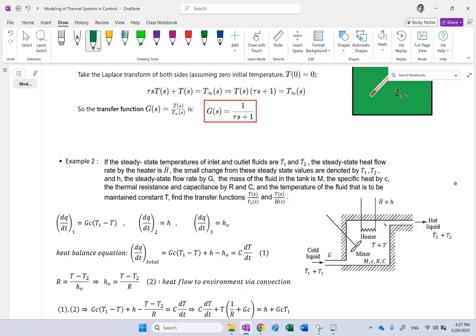One is that you have a heater in the system, and that heater is a heat source, and it generates heat and makes the system temperature go up, where the system stores that like a capacitor. Another way that the system exchanges heat with the environment is through convection or conduction with the environment, okay? So that you can model by a resistance.